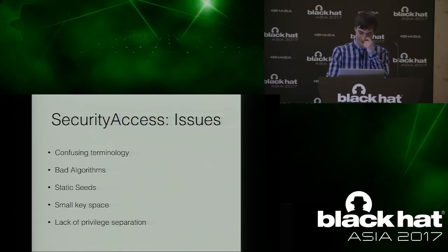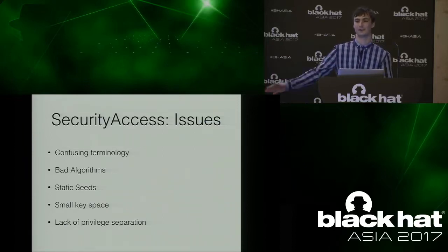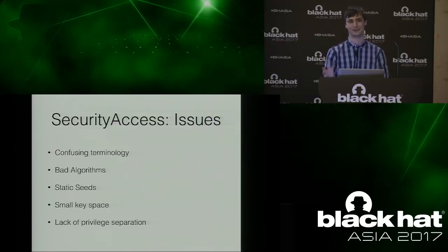And we have an example of that. Then there's a lack of privilege separation. The spec allows you to have multiple security access levels, and the idea here is maybe one is for programming, one is for diagnostics that a service technician does, and one is for end-of-life deployment. Often the only one that's separate is that end-of-life deployment, and that's only because a standard specifies that it has to be a separate level. Everything else, they just use kind of level 1, and once you're in, you get everything.